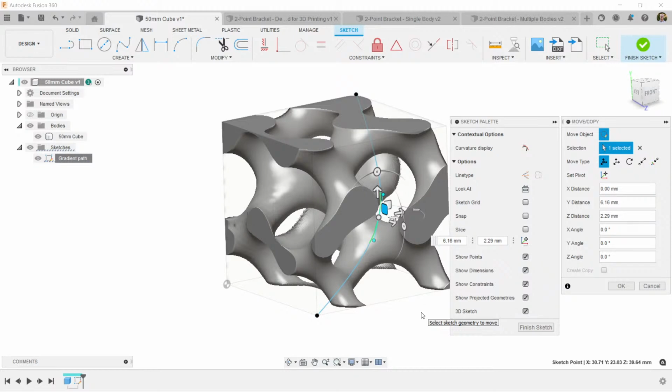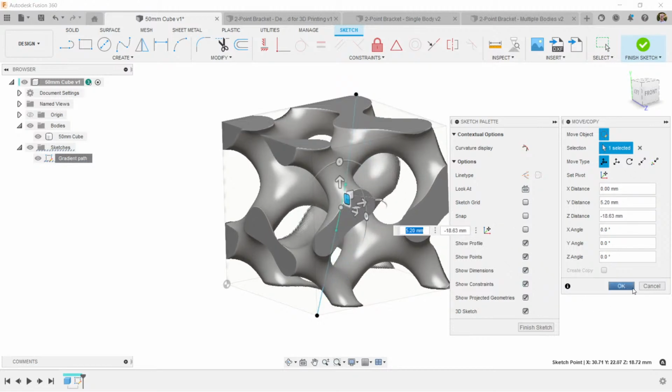So this is not a mesh at the moment. This is still a solid body, but because of that volumetric kernel, it's defining this as more than just the outer boundaries. You've probably seen in other videos, we call solid bodies boundary representational solids, or BREPs. And that's really because we're defining the object based on those boundaries. But what the volumetric kernel is doing is letting you define not just the boundaries, but what's happening inside it. And that's, of course, the lattice structure that we're playing with right now.